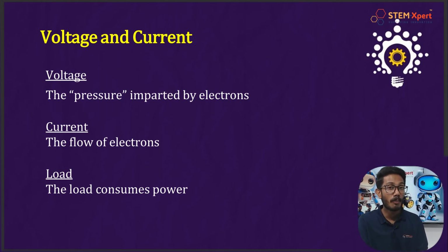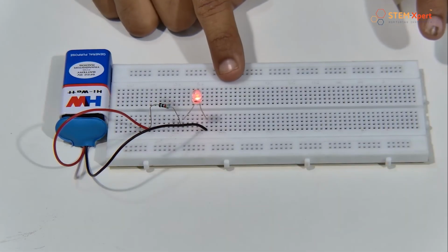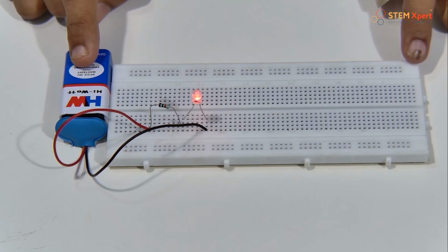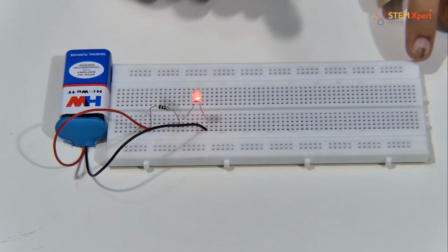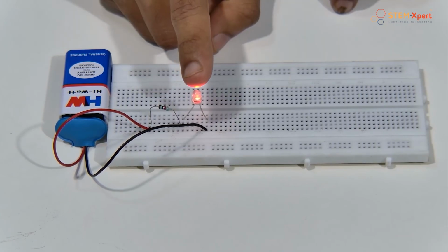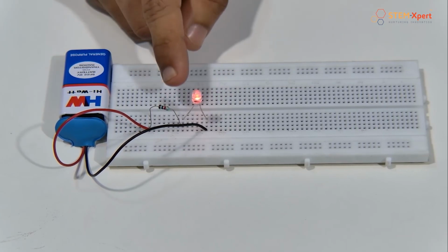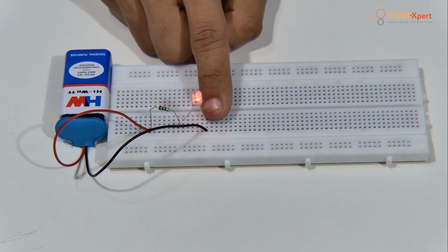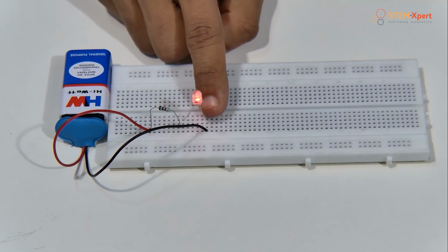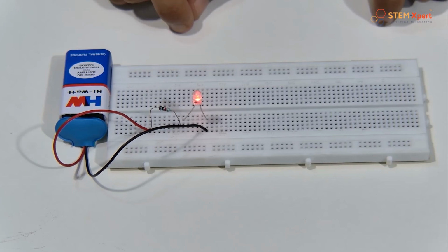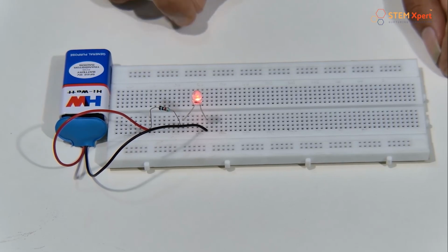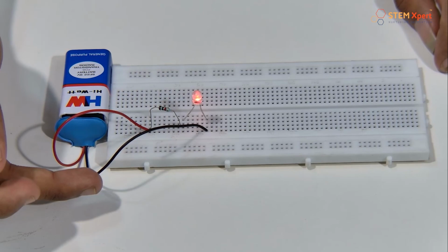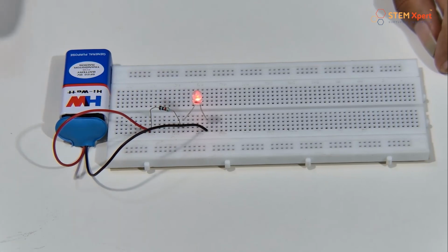So, which are the components that we have used in our circuit? We used a breadboard, a 9-volt battery and battery clip, a resistor and an LED, right? So, what's the full form of LED? Light emitting diode. Also, we learned it has two terminals, one positive and one negative. The larger one is positive and the smaller one is negative, right? Yes. Also, one important thing: the LED works only if the positive is connected to the positive of the battery and the negative is connected to the negative of the battery.